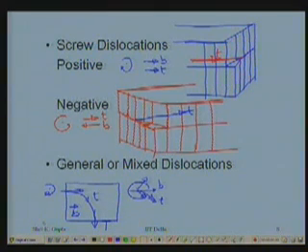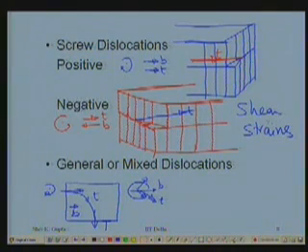Well, in the case of screw dislocations, we had the shear stresses or shear strains around the dislocation. That's the dislocation. Here bonds are strained because one atom is here, another one is there, which were actually bonded like this earlier. They were bonded like this. Now the bond is sheared. Instead of a vertical bond, it has become slightly tilted, right?